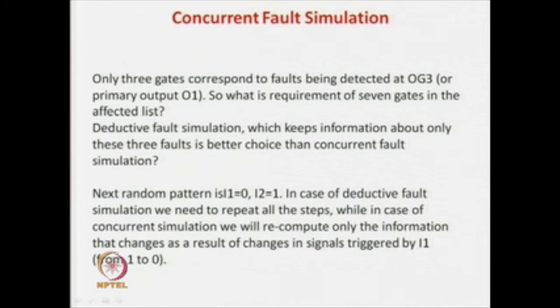The idea here was that whenever there is a change in the random pattern, those dead gates may help in detecting some other faults which we have seen, and then this recomputation is saved. That is the idea of concurrent fault simulation over deductive fault simulation. In deductive fault simulation, we do not carry anything.